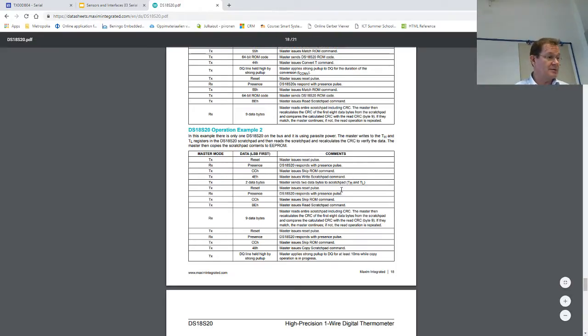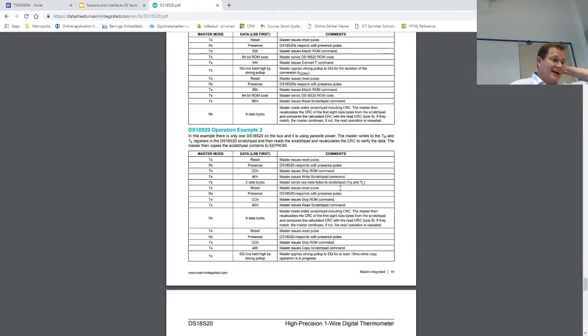with that device you will be learning how to read the temperature. It's not that hard actually. You just follow this protocol. What has to be done? Just writing bytes and reading bytes. And how to get the data basically when you read the scratch pad.